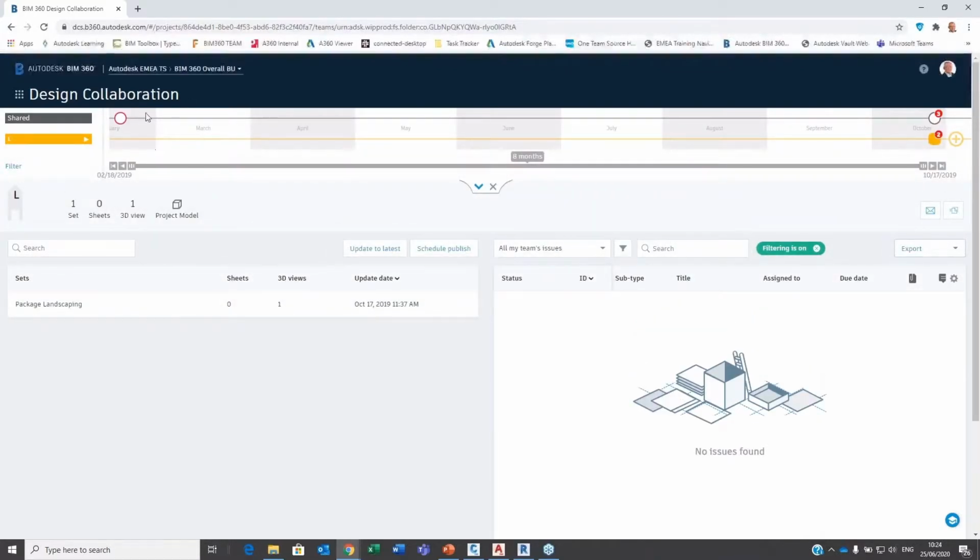So if you want to be looking at these milestones, those bulbs are the milestones, and you want to create packages, that's where you do need a BIM 360 design entitlement. And that's why in the PowerPoint, it says there's 3 components, if you will. Design comes automatically with Docs. That was the middle one. So that's fine. But to the left, you had the Revit interface, but that was specifically, again, for worksharing. Okay. And to the right, you had the design collaboration module. So if any of those left or right things are needed, then we're talking about a BIM 360 design entitlement.